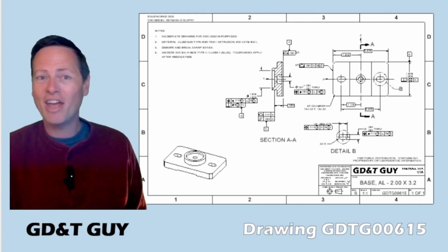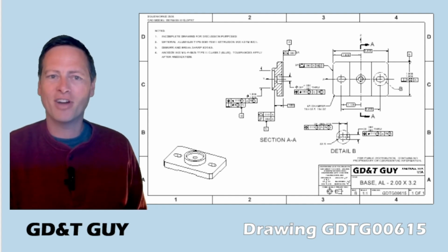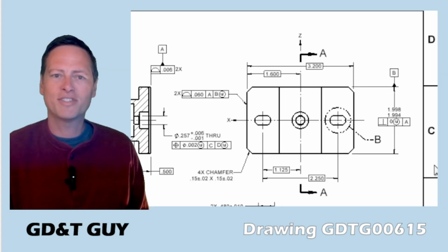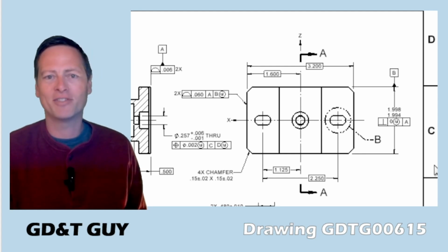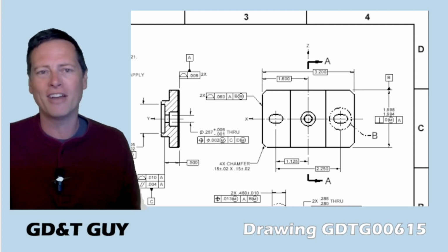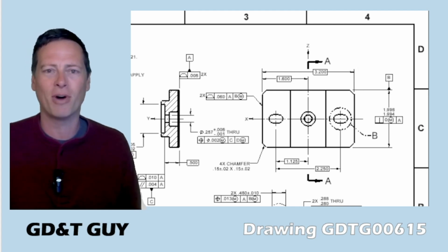And then at the very end of episode 2, I teased this drawing GD&T 00615, in which I addressed the things that make me uncomfortable about 614. So now we have basic dimensions for the width, now 3.2 inches, and a 2x profile tolerance on those ends. This seems to me to be an even more ironclad declaration of simultaneous requirements.